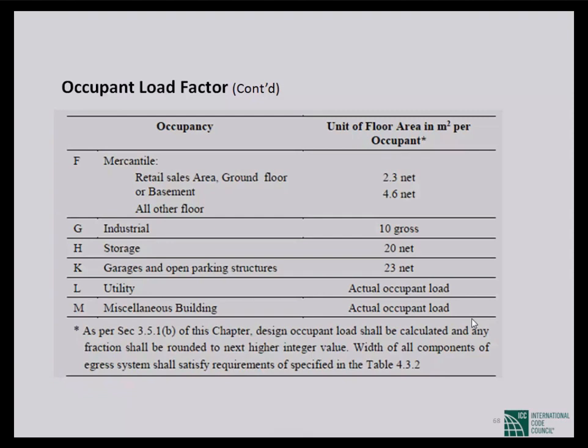If this density is 10 meter per person, a garments factory cannot run, because a person working at a sewing machine has to hand over the product to the next person by moving. But if it is a 10-meter gap, productivity cannot be achieved. Actually, that is not correct as per NFPA also. So for garments, you need some special consideration. That's why as per BNBC, you need a performance-based design. Though it is G for 10, it is not acceptable, particularly in the area of the sewing floor. Other than the sewing floor, it is fine.